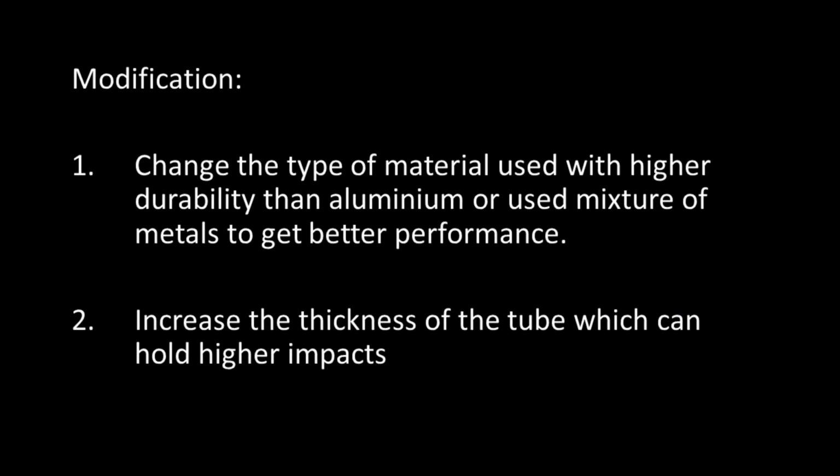Based on this analysis for this design, in order to have a better performance and higher strength to withstand higher force applied, we can make some modifications. First, we can change the type of material used to one with higher durability than aluminum, or use a mixture of metals to get better performance. Next, the designer can also increase the thickness of the tube, which can hold higher impacts.